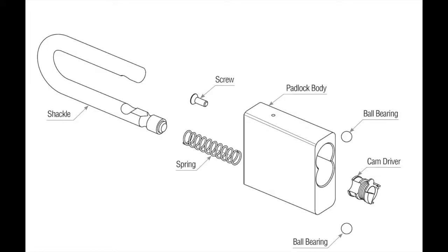For the geometric construction and design of the padlock, we chose a U-shape. The reasoning for this U-shape is to easily latch onto a plethora of objects, as it can be easily threaded through holes. This design is relatively compact as well, as there's no edges sticking out. This U-shape can be of different lengths and widths based on the purpose of the padlock. A larger diameter shackle is more secure, as there's more material to cut through. However, the smaller it is, the more versatile it is, as you can thread it through more objects.